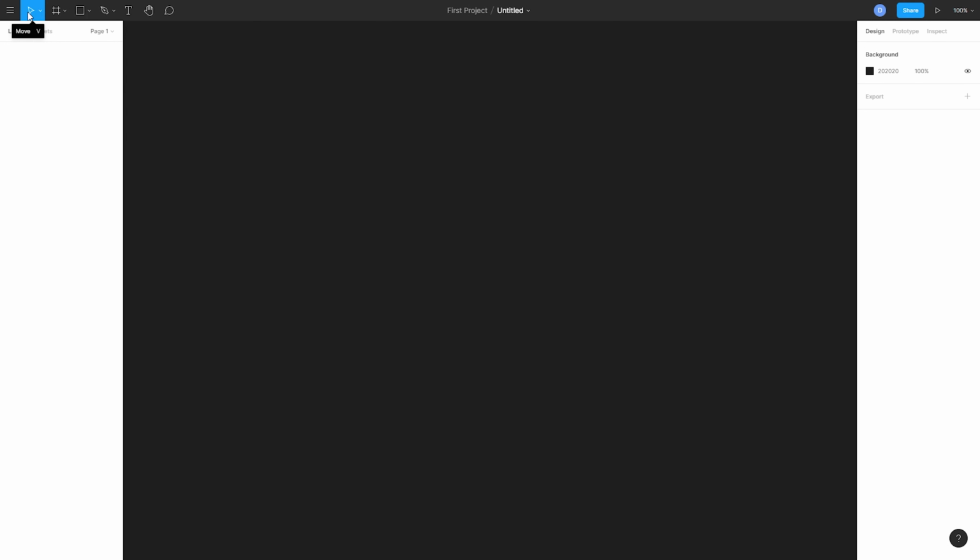So the first real tool is the move tool. If we click the little arrow next to the move tool, we can reveal the other tool which is similar to the move tool, which is called scale. We can also see the shortcuts that can be used to get to these tools quicker. If you press V, we'll get to the move tool. See, that changes. And if we press K, we'll get to the scale tool, like that.